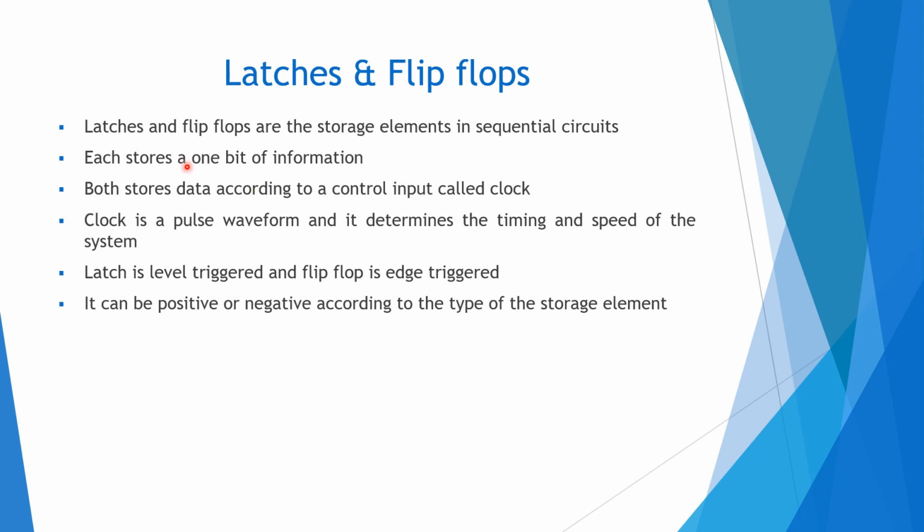So latches and flip-flops are the storage elements in sequential circuits. Each stores 1 bit of information. As I told you, if you want to store 1 byte of information, we group 8 flip-flops, in which each flip-flop stores 1 bit. Both store data according to the control input called clock, and both respond to the input according to the clock. Clock is nothing but a pulse waveform, and it determines the timing and speed of the system. You have already seen the clock of a processor, like the AMD Ryzen 5.